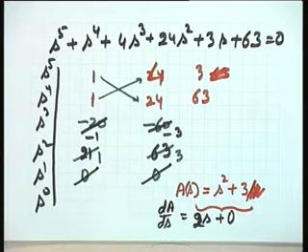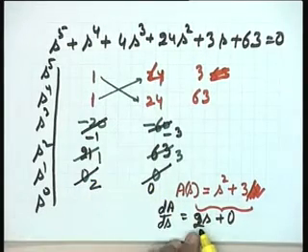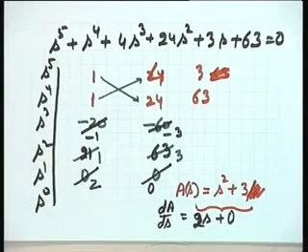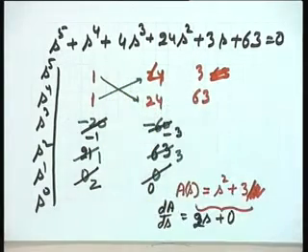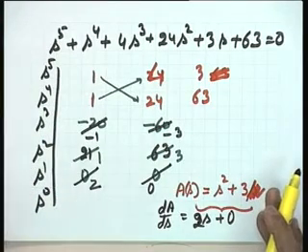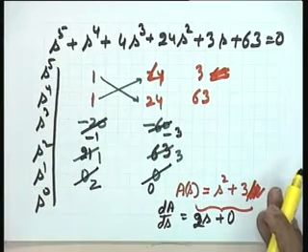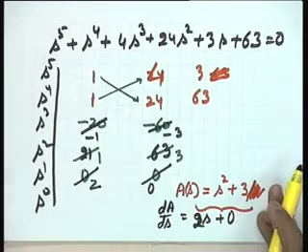So what are the coefficients? 2 and 0: the coefficients of the derivative of the auxiliary polynomial, 2 corresponding to s to the power of 1, and 0 being the missing term. Now you continue with the Routh array formulation, and all the conclusions which you now get from the first column are actually valid on the remainder polynomial. Please complete it and give me the conclusions.